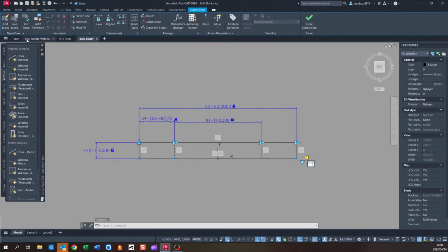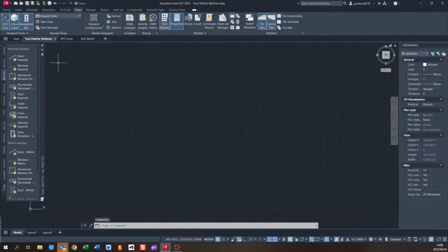So you don't have to jump to another drawing. You don't have to select anything else but open the tool palette, and it will appear on all of your drawings in the relevant AutoCAD version. Okay, so the changes you make in AutoCAD 2023 won't be present in AutoCAD 2024 unless you've actually migrated all of those custom settings.